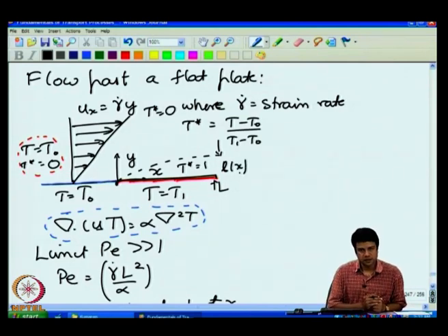The velocity profile has to be linear over a length scale comparable to the boundary layer thickness. So long as the boundary layer thickness is small compared to the macro scale, the velocity has to come down to 0 at the surface anyway. So, near the surface the velocity has to increase linearly from 0, and if you are expanding in a thin region in a Taylor series expansion, the first term in that expansion will be the linear term.